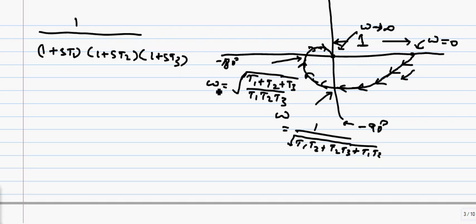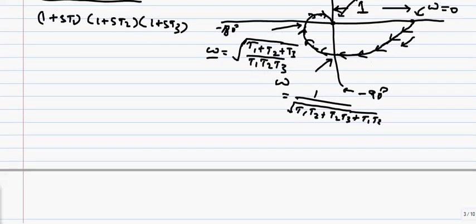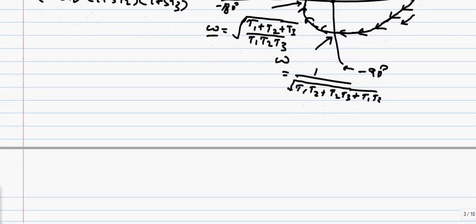That is the reason why, if you just know the frequency at which it crosses, we can easily calculate the magnitude and say whether it is encircling minus 1 or not, and say whether the system is stable or not. And we use these concepts even in calculating gain margin and phase margin. We'll come across this later in the videos.